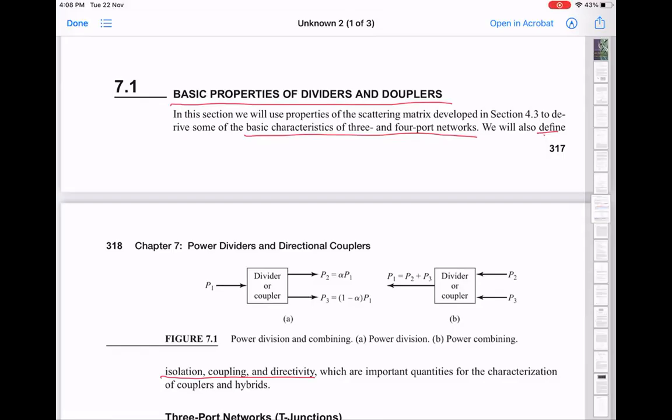But again, here we are going to be thinking in terms of waves for at least some of the aspects. So this power combining operation is in general not an ideal operation in all cases. We will come to that later on, but I've already mentioned this to you in the context of the demos that if the signals are in phase, then they will come out of what was the input port earlier without any power loss. But if they are in general 2 independent signals, then you will not get a lossless combination of 2 signals.